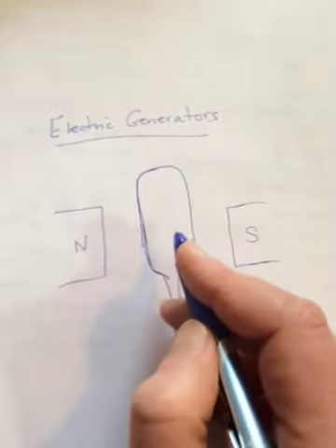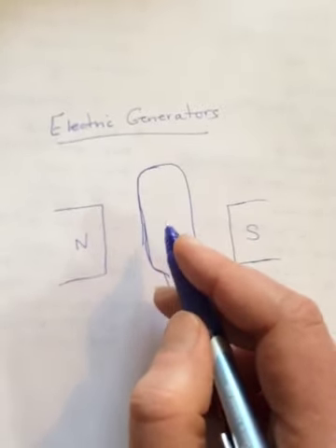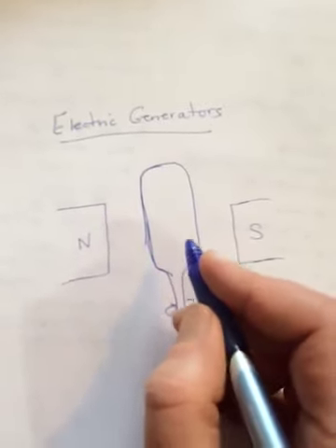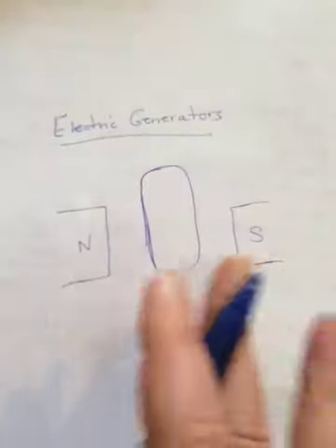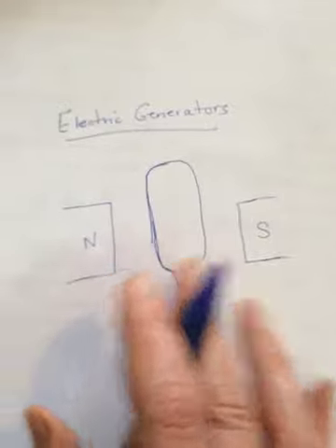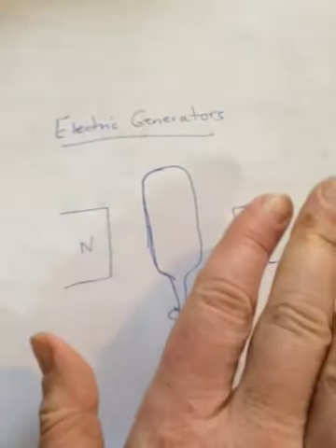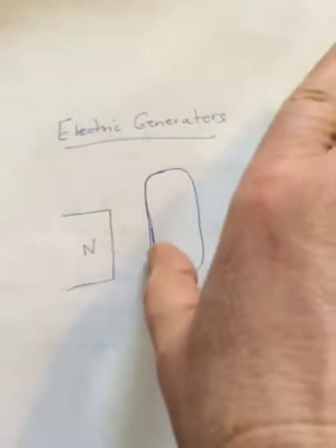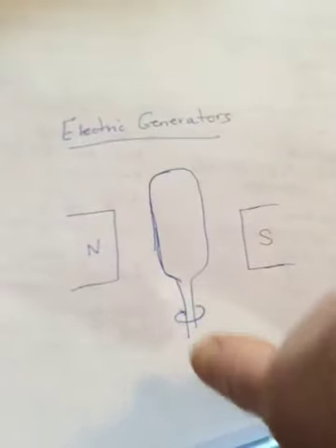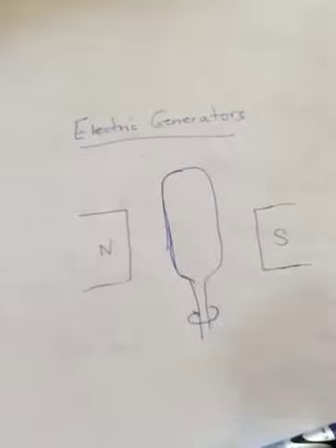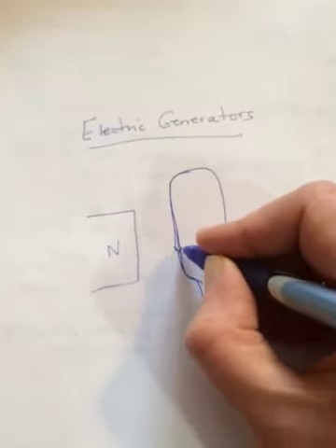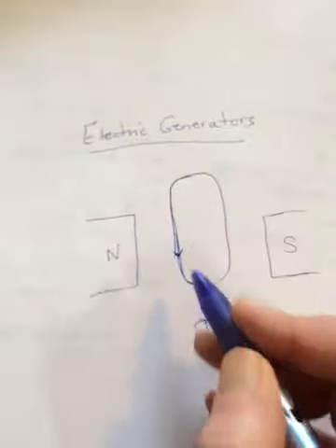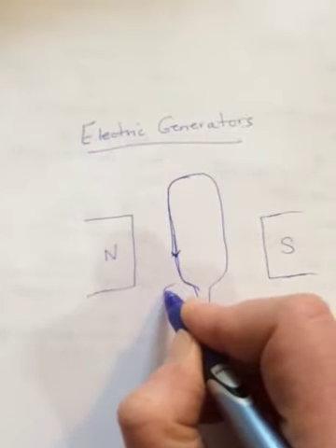And a wire moving in a magnetic field is going to get an induced EMF and have a current flowing in it. I have to use conventional current because I'm using my left hand to hold the iPad. So if we think conventional current, the wire on this side is going down. My fingers have to go north to south. I can't show you that. And so the induced conventional current would flow this way. Okay, so this is going to go down into the page.